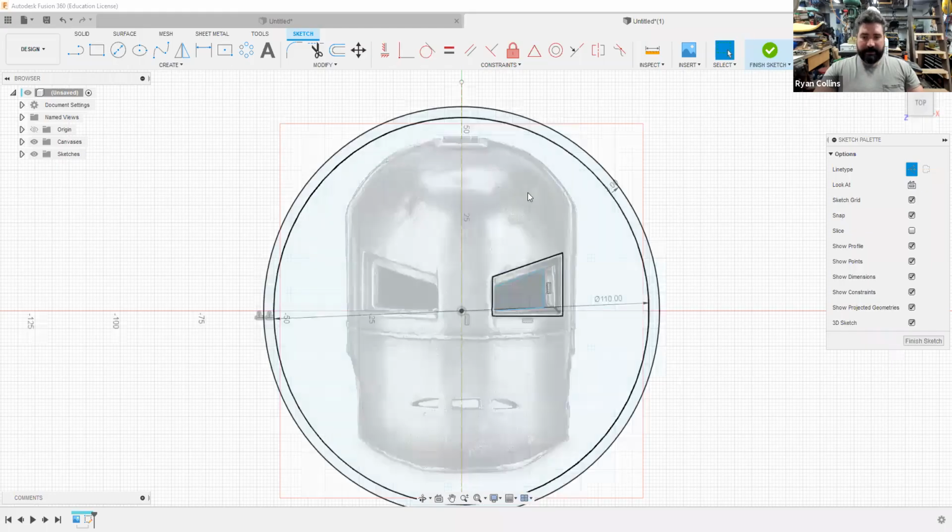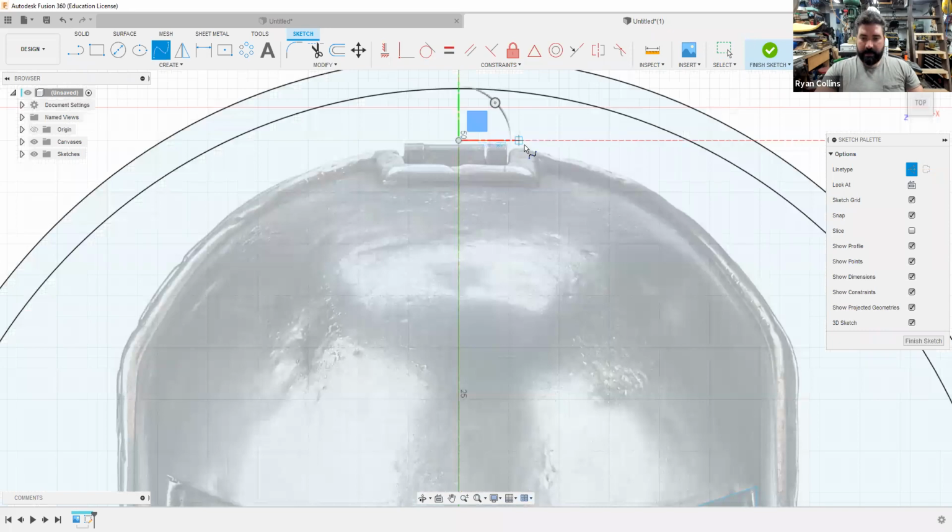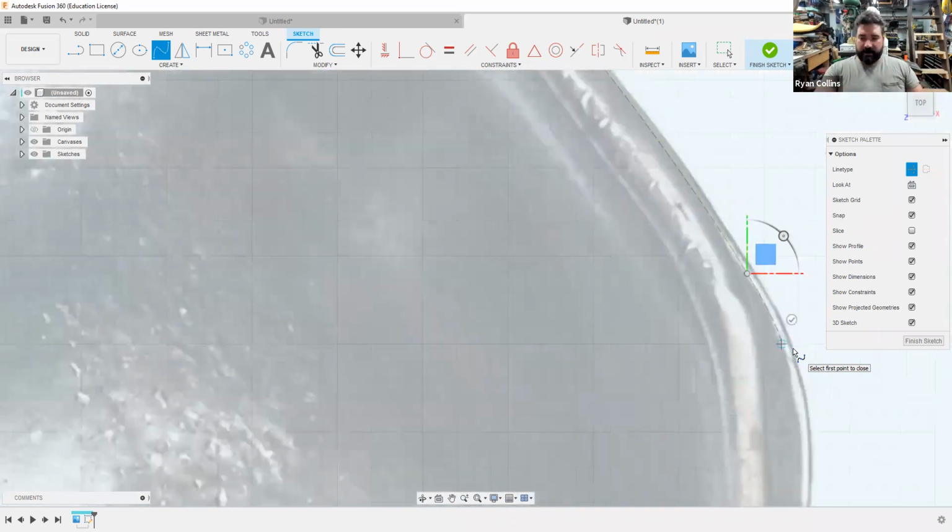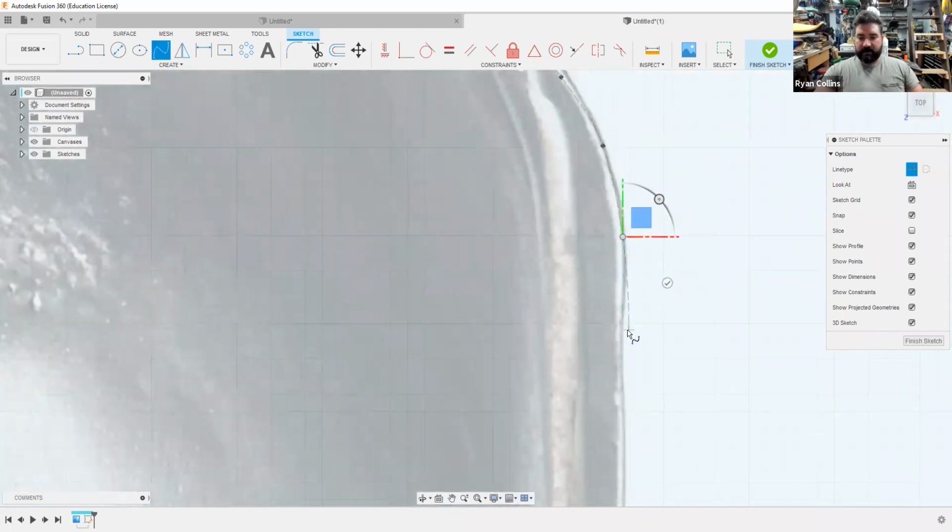So to make this upper line here, I just want to show you a few details for making the overall outline and such. I'm going to use a fit point spline for the upper line there. Start about up in the center, and I'm just going to trace along as best I can. Now, remember what I said about being able to use those handlebars and things like that? This is definitely where you start to learn where it's important to put more points and fewer points. Fewer points, you're going to get a much smoother, longer arc. More points closer together is how you create tighter spots. And remember, you can always change these around later.